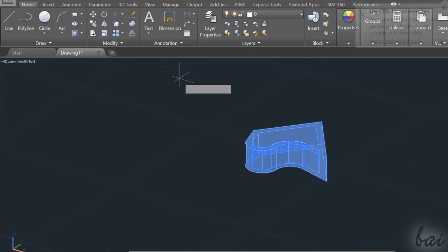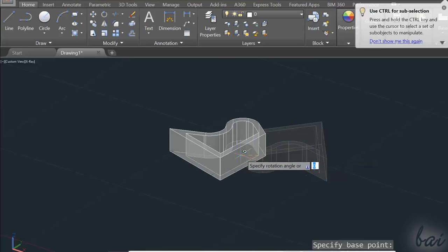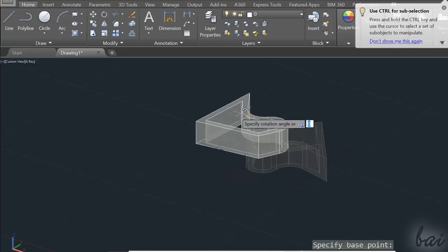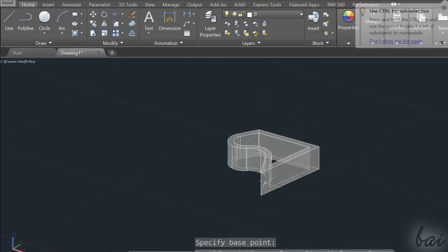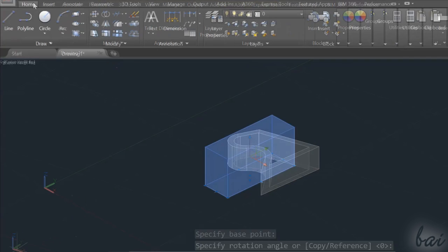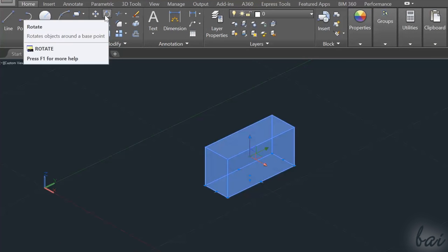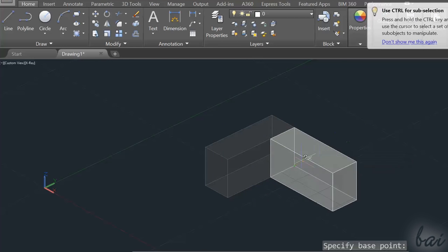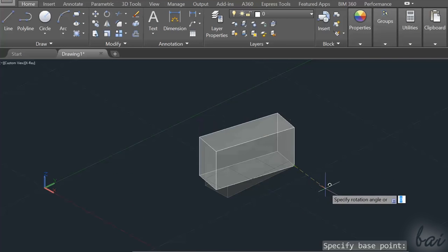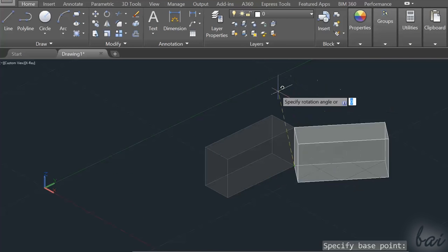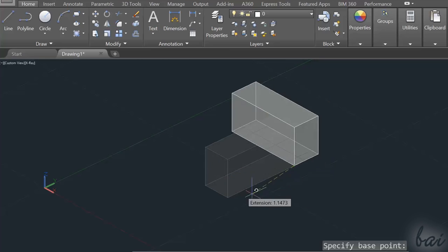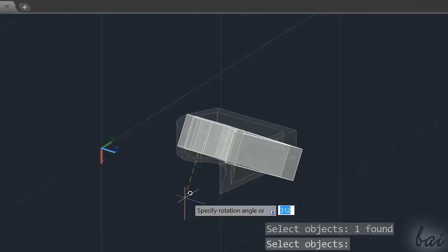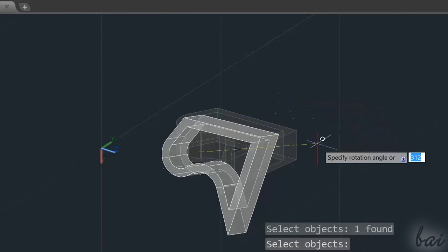Apart from the gizmo system and the nodes, you can edit your 3D objects by using most of the tools seen for 2D objects inside the Modify section. Remember that these will act always respect to the ground plane only, so on the 3D object base if this has it. For example, if you use the Rotate tool on a cube, you will be able to rotate it respect to the ground plane only, unless you rotate the overall gizmo system of the project.